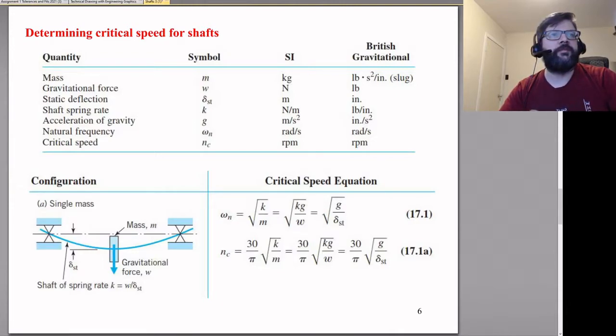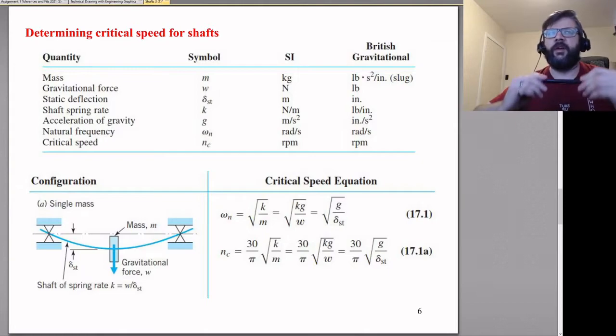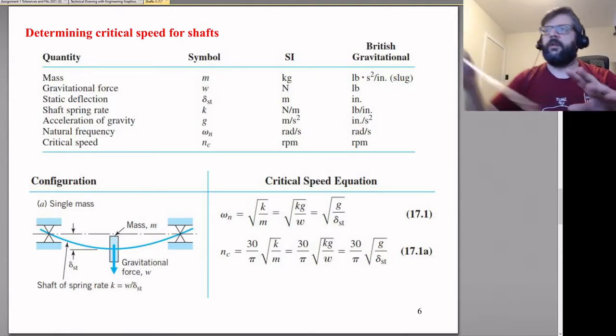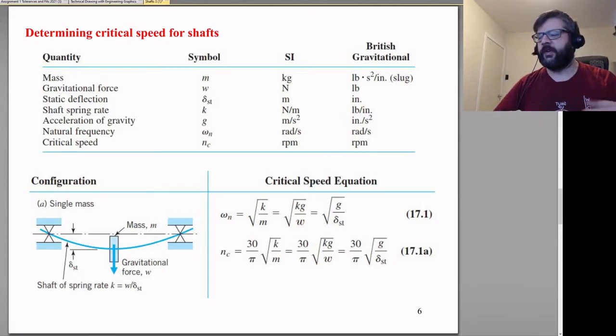So, welcome back. As you saw there, the critical speed is a speed at which we have a tendency to get excessive deflection of the shaft that is rotating. One of the key aspects here is that being above the critical speed is not necessarily a problem, because at a particular speed you have a tendency for the deflections in the beam to take a shape like this.